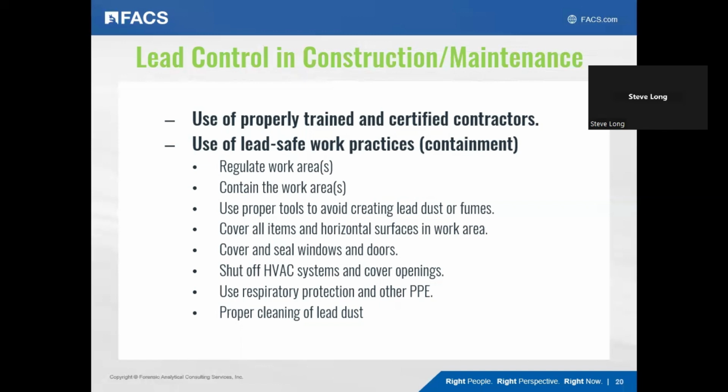So looking at the steps for that, first would be regulating the work area. So this would be accomplished typically with signage, warning people away, with barrier tape to keep people who shouldn't be in the area out of the work area. And also it serves as a boundary for workers to make sure that as they're leaving the work area, they clean themselves and are not tracking any lead outside of the work area.